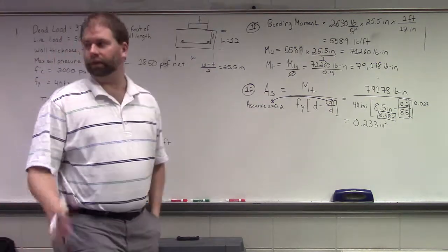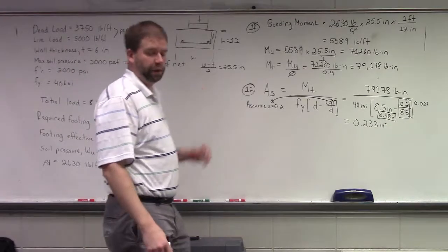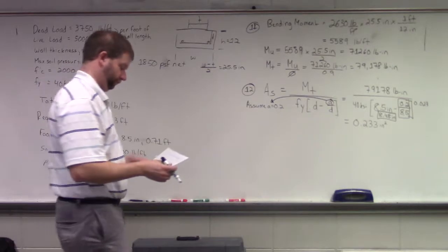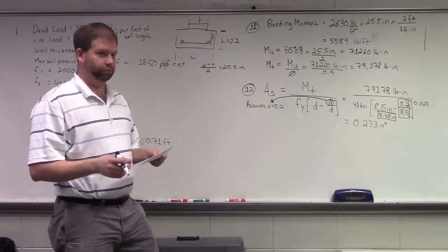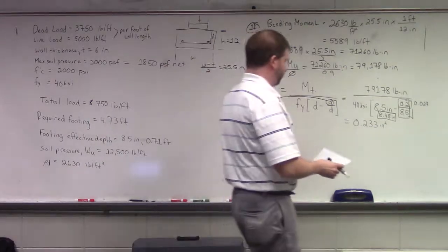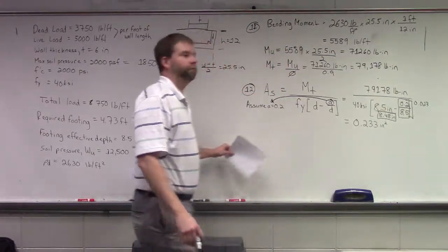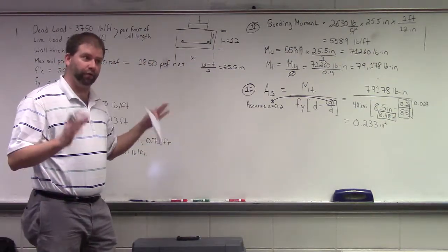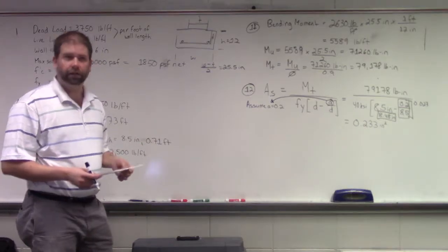So then multiply it by 144. Yep, I got that. Okay, 1, 2, 3, 3. Okay, I got that. And that's in inches squared, right? It's the area still. Yep. And that is the rebar, that's the total area of rebar that you need.